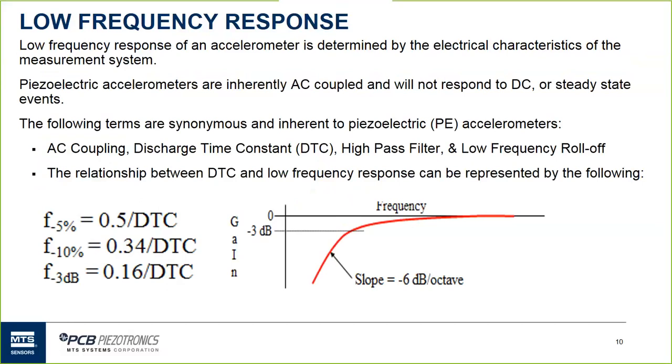So let's take a look at what governs the low frequency response. Low frequency response is governed by the electrical system of the transducer, and that relates typically to what we refer to as discharge time constant.